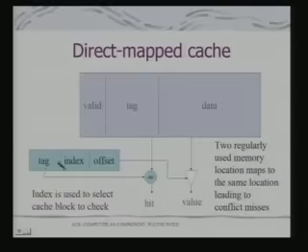For that purpose, the address that is being generated by the processor is logically divided into these blocks. We call it the tag, index, offset block. So, this is the division of the memory address that is being generated by the processor. So, this is your cache block. In the cache block, what do you store? You store data definitely, and there can be multiple bytes of data stored in a block, but along with it you store the tag and another bit, a valid bit, which tells you whether the cache block contains really the data from the main memory or it is just junk.